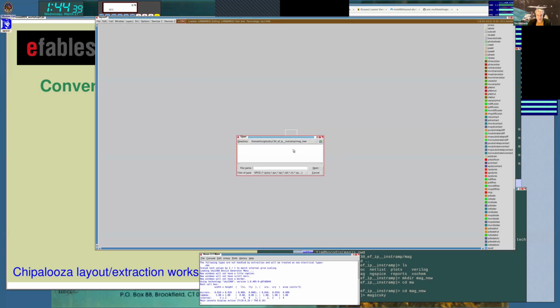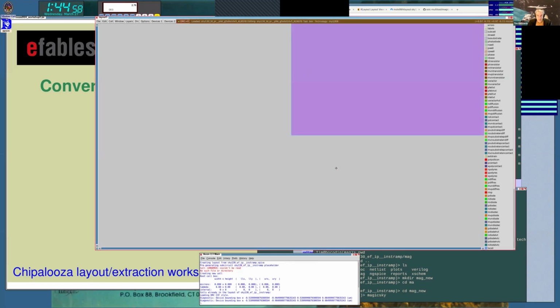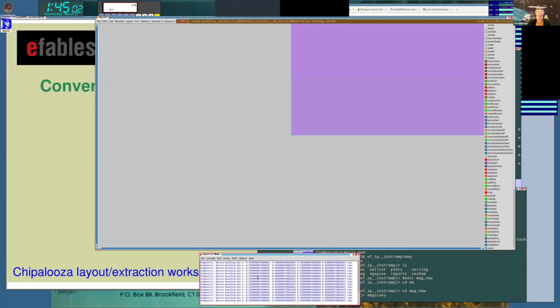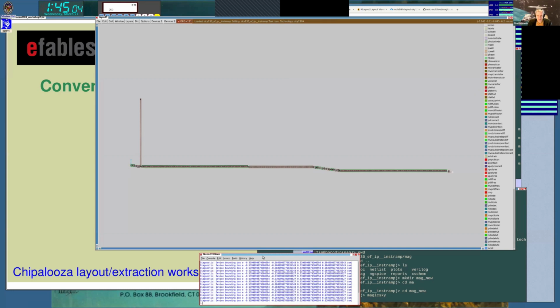So I click on Import Spice. This is something I did for CASE. So I've got the usual CASE-derived file structure in which it put things in netlist, schematic, and there's my Spice netlist for the device, for this IP. And when I say open, you'll see it's doing a lot of work now. So now it's actually looking through the file and creating all the devices.